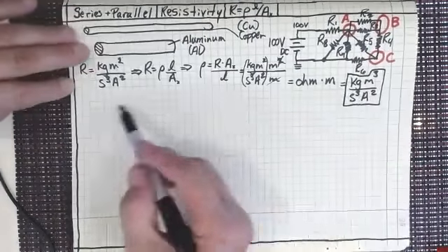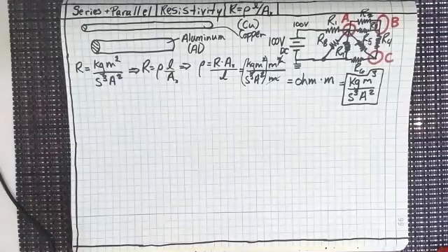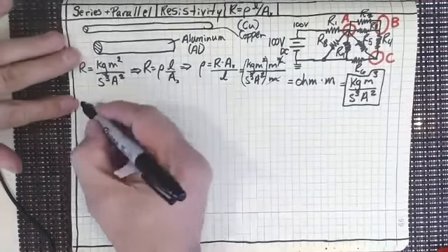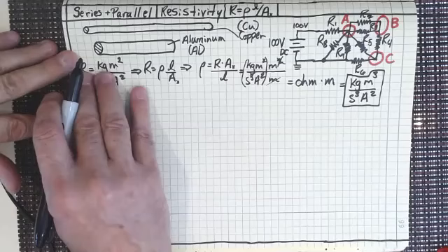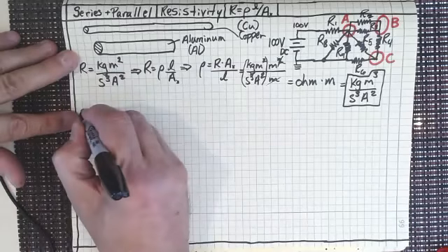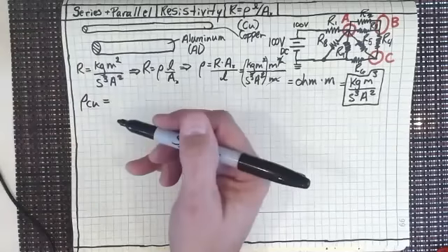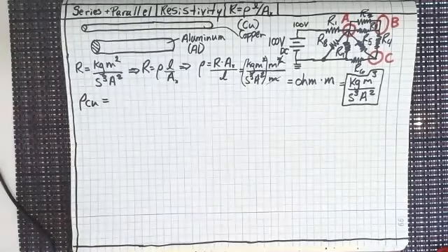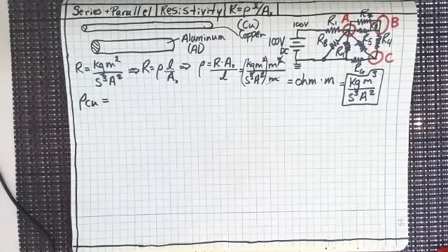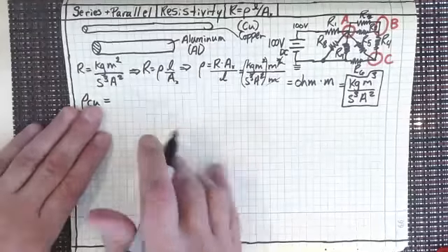So that's what resistivity is. And I want to look at resistance for two different types of things. The resistivity for copper, and I'm going to use the one in your book, although I don't really use this. I use 16 ohm nanometers, or 16 times 10 to the minus 9 ohm meters, is the way that I usually look at it. But let's just do that.